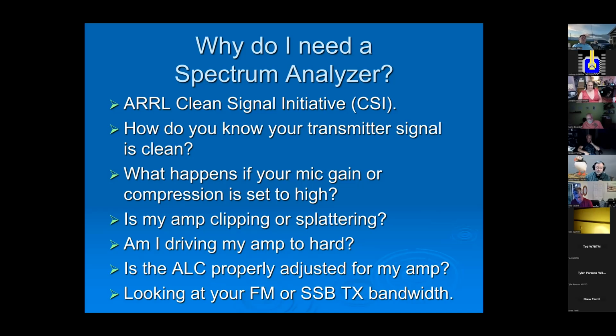If you're running an amp, got clipping and splatter, same thing. Are you driving it too hard? Are you over modulating it? Do you have a bad set of filters in there? So you want to know the same kind of information for your amp.